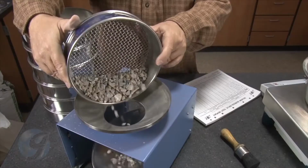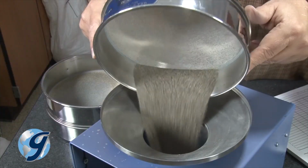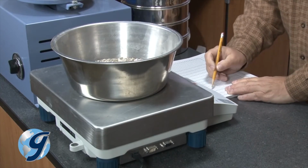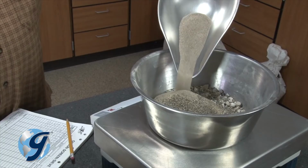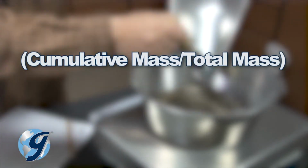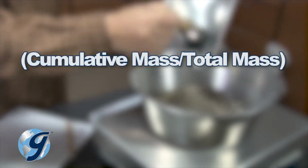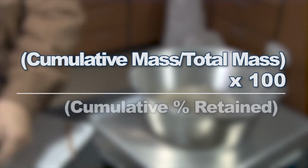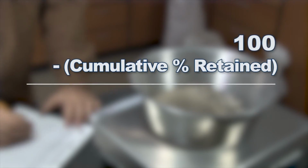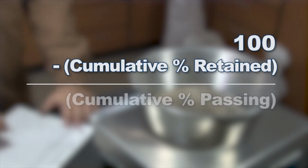For the cumulative method, each sieve fraction, beginning with the coarsest, is placed in a previously tared pan and weighed. As each retained fraction is added, divide the cumulative mass by the total mass of the sample and then multiply by 100 to calculate the percent retained. Subtract the cumulative percent retained on a given sieve from 100 to calculate the percent passing.